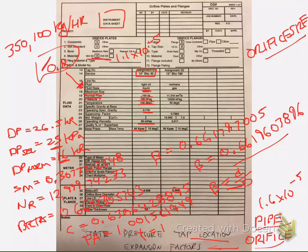And so now I need to just multiply that by 10 inches times 24.5, and so I get an orifice size, our little d, this is kind of our final answer, is 168.137939 millimeters. So that's our orifice plate size approximately. Orifice plates also come in standard sizes, so we're going to be picking one closest to that value.